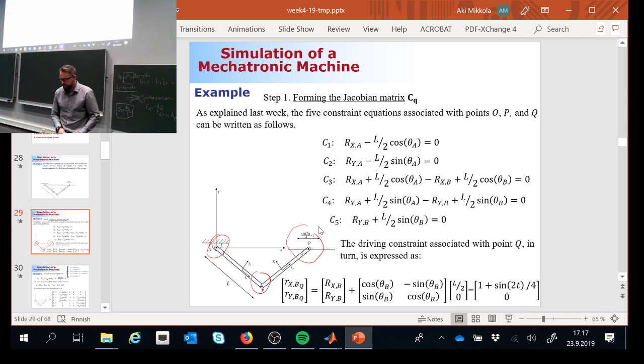All right. Now, we already have these 5 constraints. The one remaining constraint is associated with the driven constraint. Now the driven constraint, look at this. This is important. I'm constraining the motion along the global y-axis. That's why I have this driven equation placed in a position where the x position is expressed.